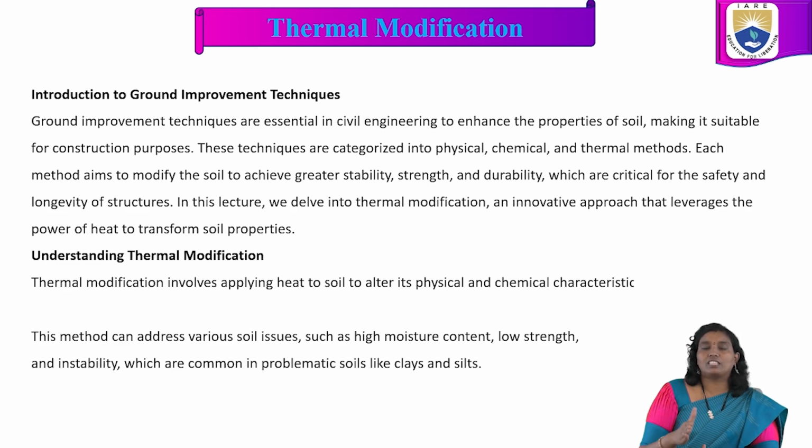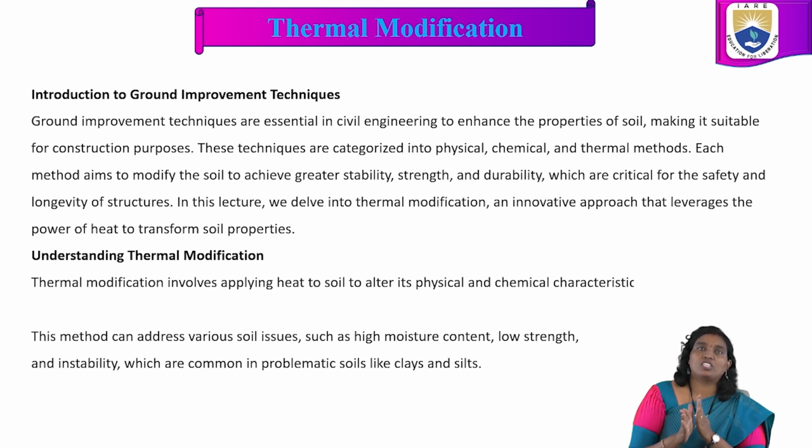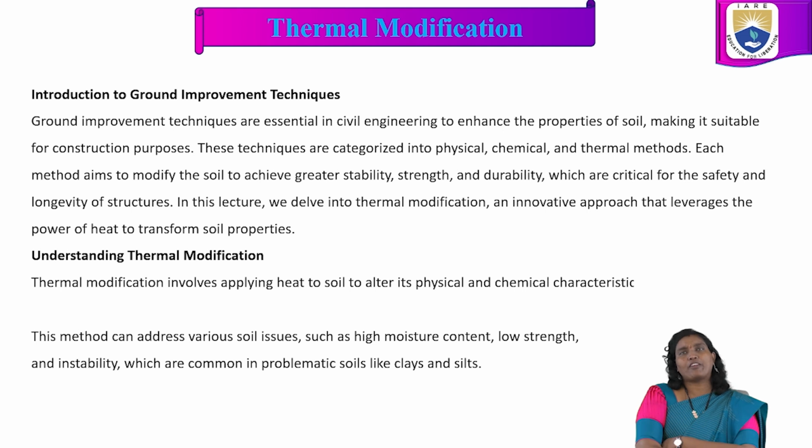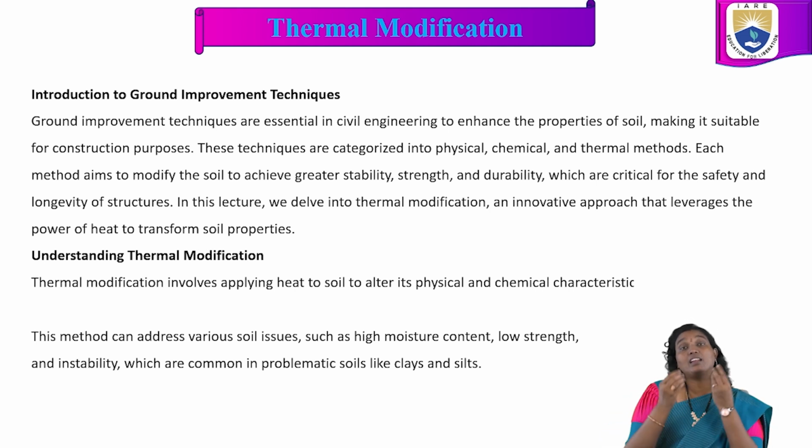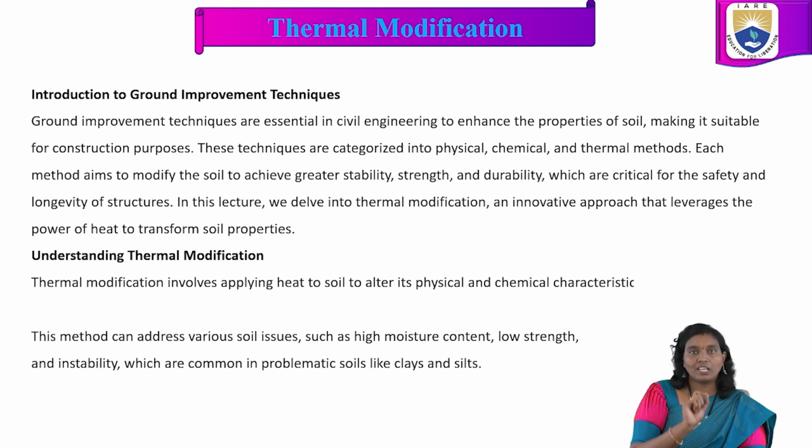In this lecture, we are going to understand thermal modification, an innovative approach that leverages the power of heat to transform soil properties. Thermal modification involves applying heat to soil to alter its physical and chemical characteristics, and even small changes may affect the property of the soil.